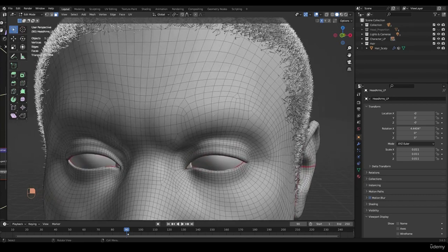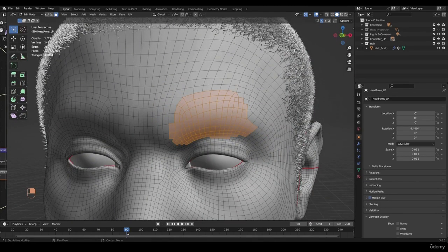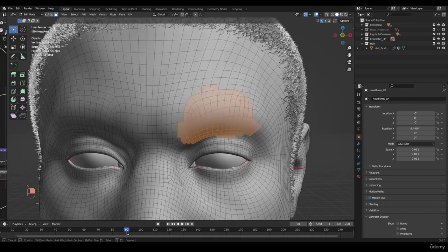Press C as in cat on your keyboard, and then select some geometry here. Right now we are on Paint Select. You could hit Escape on your keyboard to get out of the Paint Select, and now you're able to navigate again. But press C again. So just select some areas that you want. It's best to select more than what you need.